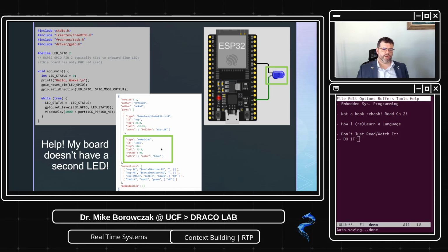So first off, the LED I already pointed out. You can easily change that attribute. LED1 is just the ID name. We'll see how that comes into play in a few moments. But we definitely have an identifier which will help us in defining connections. All right, so on the cathode of the LED here, we have LED1:C for cathode. Right, so that's right there. What's it connected to? It is connected to ESP ground.